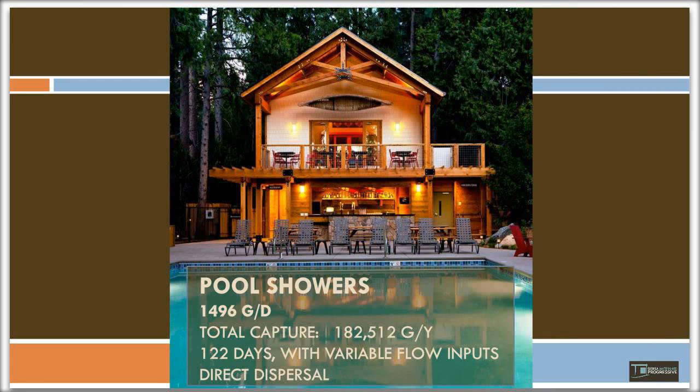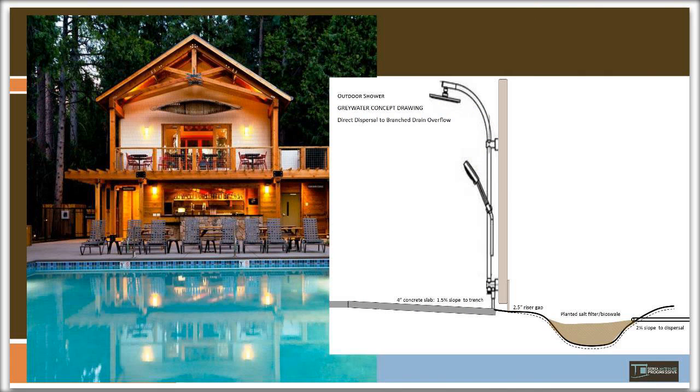And here we had a problem where they wanted to not put a covered roof over the shower, and they wanted to capture the gray water. So we just came up with a real simple slab that was sloped down, and we captured the gray water directly into a trench, and it went under a little riser gap.